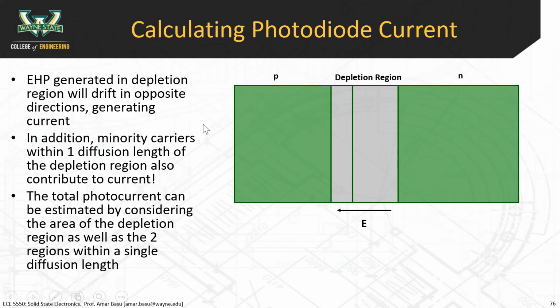So you imagine that you have a P-type material like this, and you have an N-type material like this. And I haven't drawn all the details in here. You already know what the carriers are doing. You know that there's a depletion region that forms, and I've split the depletion region up into two parts. Just as a quiz, what type of junction is this? Is this P plus N? P plus N. Why is it a P plus N junction? The depletion region on the P side is shorter than the N side.